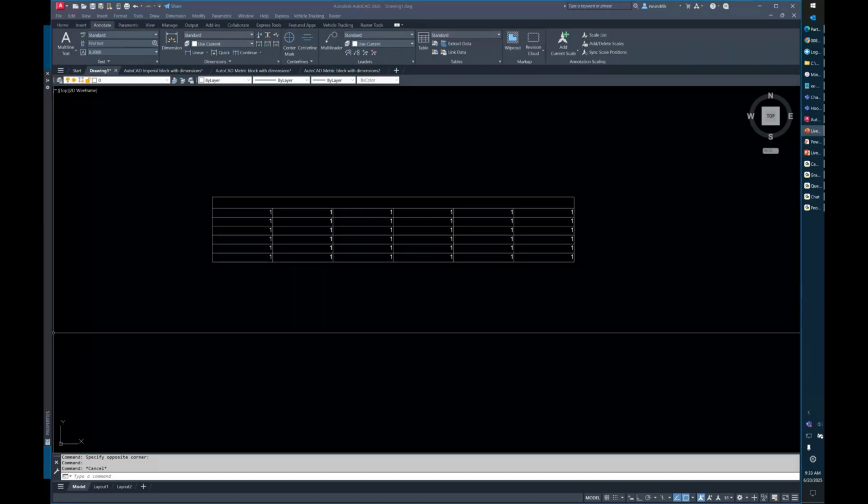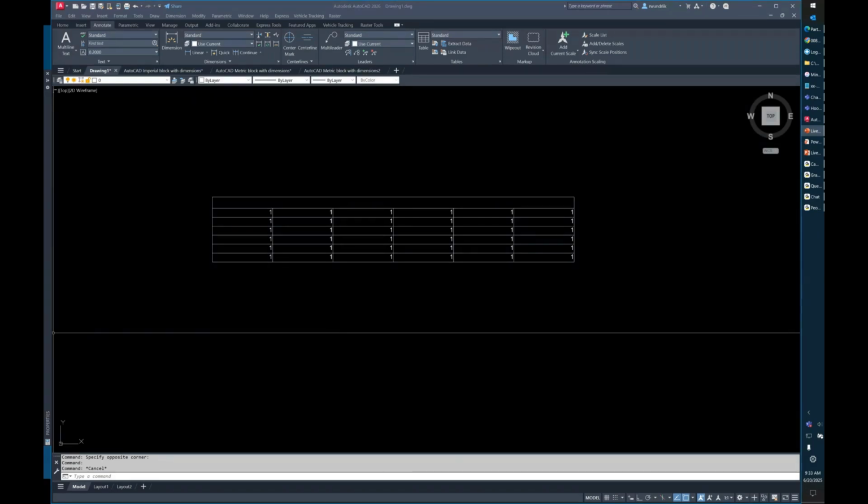All right, Karen. So what about imperial and metric tolerances? When we do dual dimensions, sometimes we have a tolerance that is a value of 0. The plus or minus symbol does not appear. To get around this, we add a number beyond the visible decimal place to fool it into appearing like that, but set to 3 decimal places. Let's make that a little bigger.